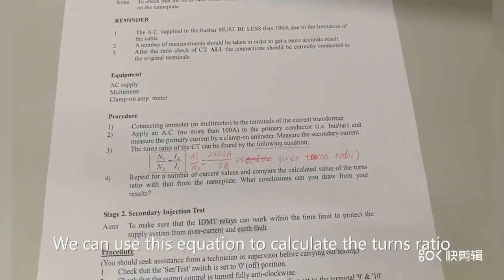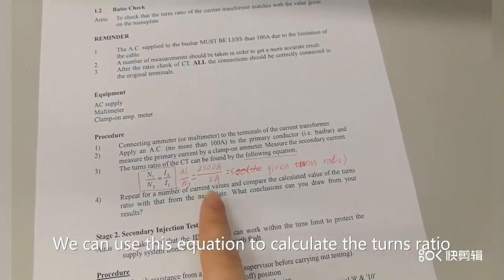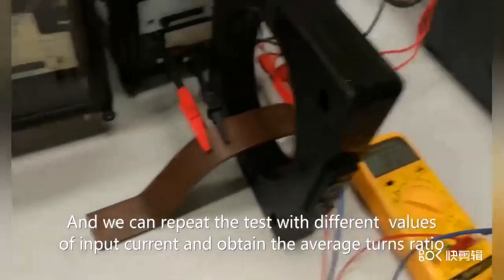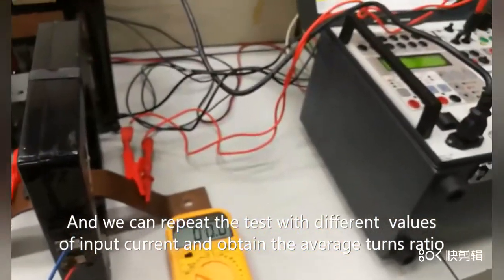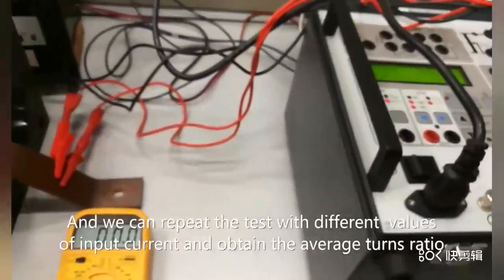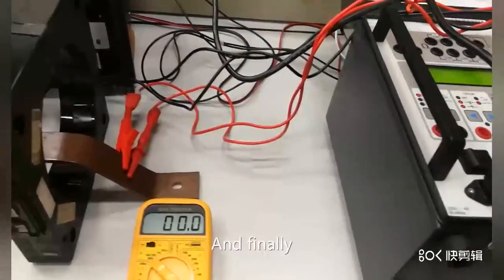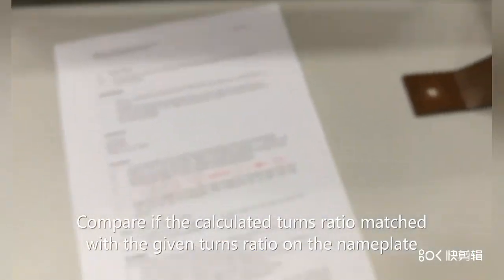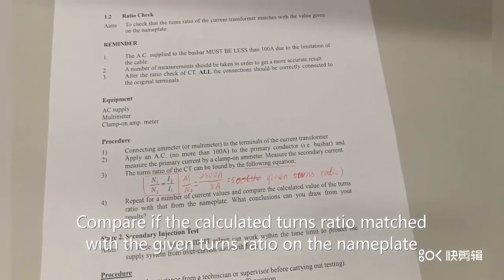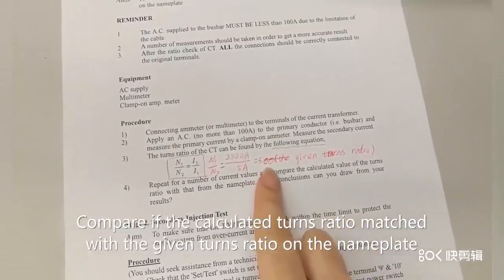For this test, we can use this equation to calculate the turns ratio, and we can repeat the test with different values of input current and obtain the average turns ratio, and finally compare whether the calculated turns ratio matches the given turns ratio.